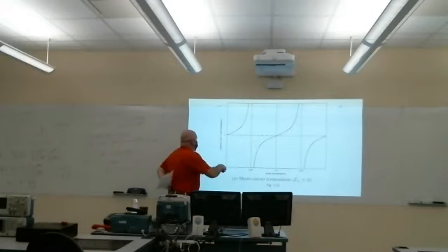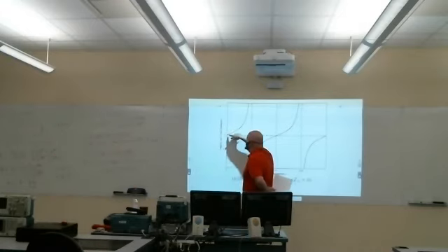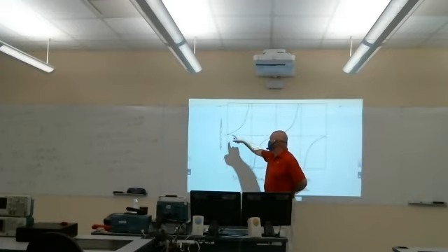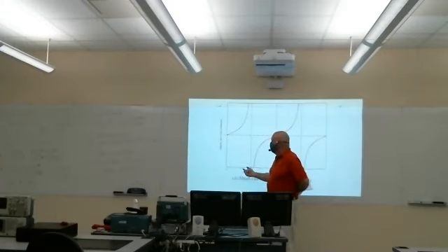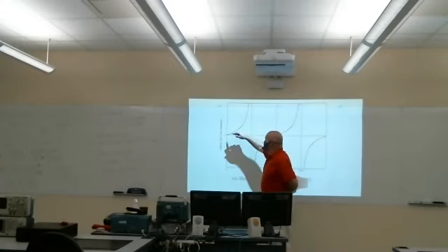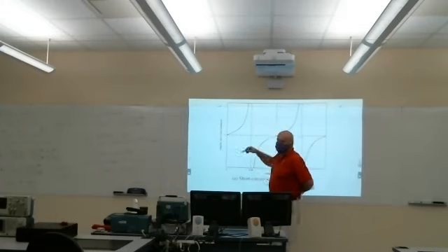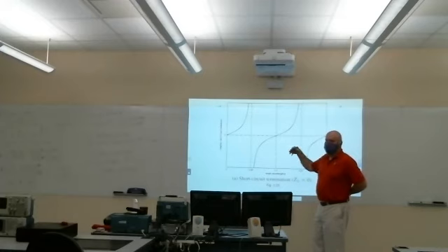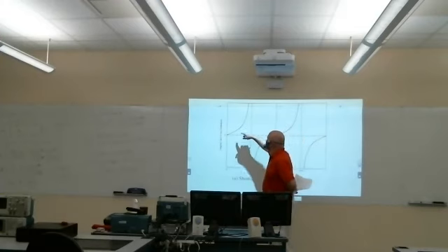So, here I'm at the load, measuring the input impedance right at the load. That's a short circuit. But between a distance of 0 to a quarter wavelength back from the load, I measure an inductive impedance, purely reactive. So in this case, the voltage and current would be 90 degrees out of phase. That's what the j does for us.